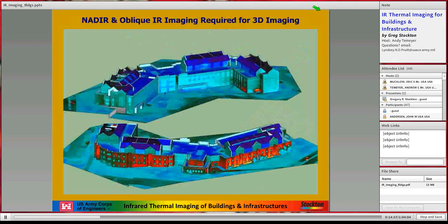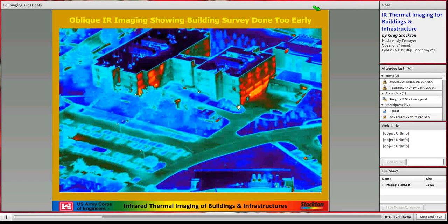And when you look at a building late at night and in the winter, and you see heat on the surfaces of the building that's warmer than the glass, because glass is a pretty miserable insulator, then you know you got problems. You can do 3D imaging of buildings. It's possible. It's much more expensive than just doing regular infrared, but some buildings warrant spending a little bit more money on for one reason or the other.